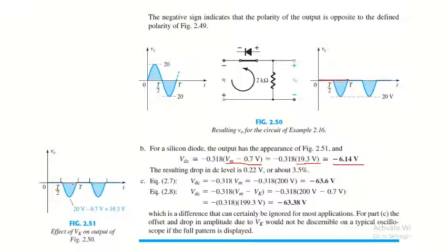The output value will be like this, because we need the input potential to reach a threshold value. We need to wait for the input signal to reach the threshold value so that the output voltage will start rising, like up to here.